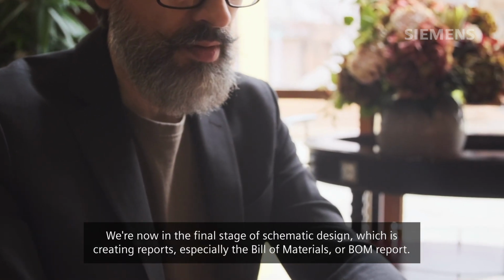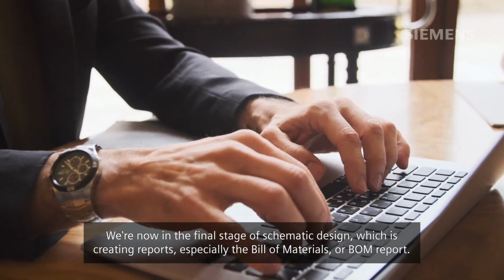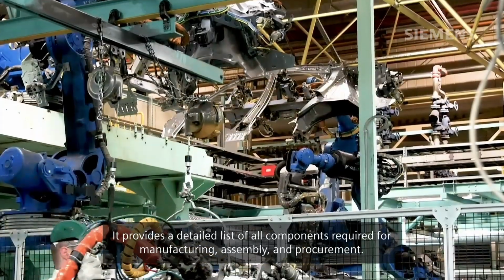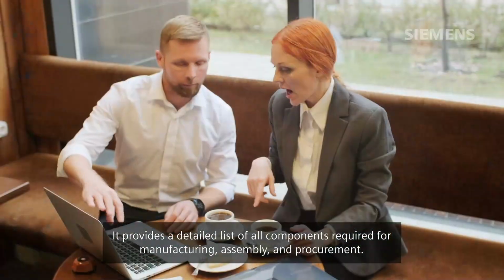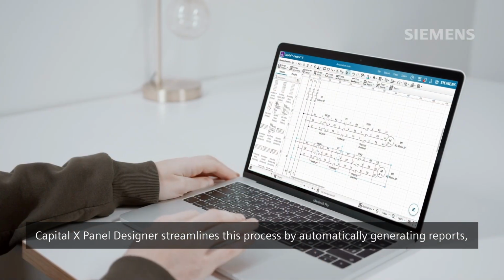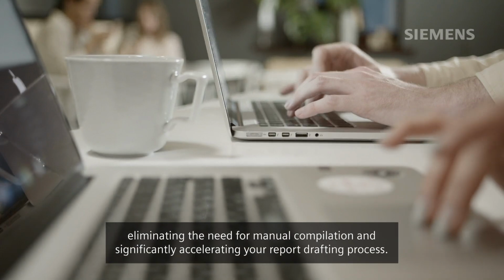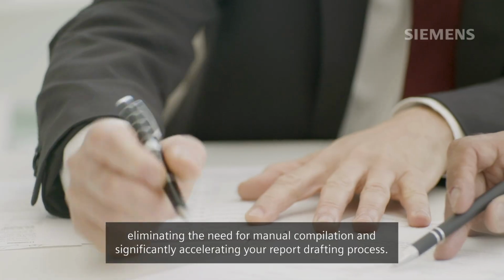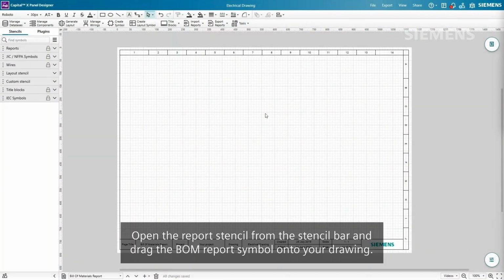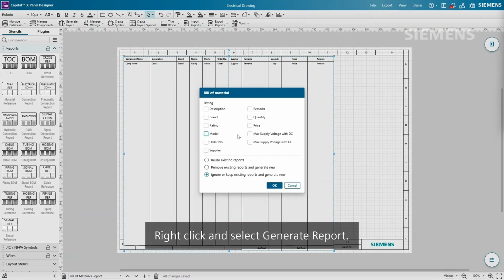We're now in the final stage of schematic design, which is creating reports, especially the Bill of Materials or BOM report. It provides a detailed list of all components required for manufacturing, assembly, and procurement. Capital X Panel Designer streamlines this process by automatically generating reports, eliminating the need for manual compilation, and significantly accelerating your report drafting process. Open the report stencil from the stencil bar and drag the BOM report symbol onto your drawing. Right-click and select Generate Report.